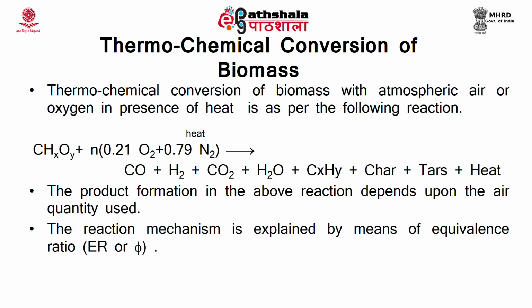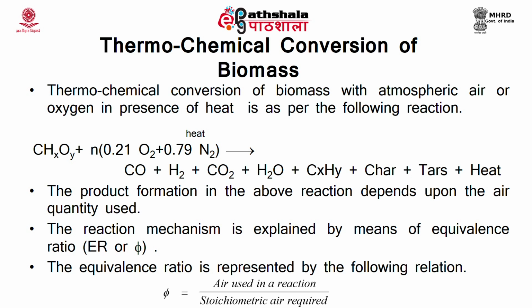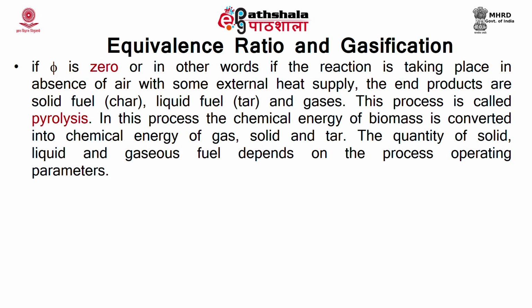The product formation in the above reaction depends upon the air quantity used. So, the reaction mechanism is explained clearly by means of equivalence ratio, which is abbreviated as ER or designated as phi. This ratio is represented by the formula phi is equal to air used in a reaction divided by stoichiometric air required. If phi is 0, or in other words, if the reaction is taking place in absence of air